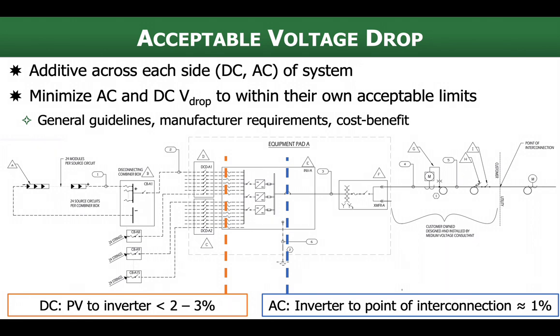So really important to keep this in mind. We've got a little more wiggle room on the DC side. It's power loss, but it's usually not extreme enough to do things like fall out of the inverter MPPT window. The AC side can be much more fickle, depending on the voltage at the site. You can get into a problem when the inverter is really pushing out a lot of current, where we run into an issue we often call voltage rise, where the terminals of the inverter see that higher voltage and it shuts off as a result.